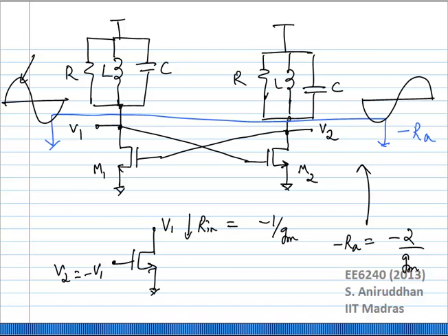Okay. Now, the asymmetry which is available between these two points, there are many different kinds of asymmetries. Obviously, if it was just mismatches between the components, that may or may not be enough to start oscillations. The reason for that is the mismatch. Let us say you have a mismatch between the transistors. All that means is that the DC operating point may be slightly different. Correct? Maybe the current does not divide exactly IT by 2, IT by 2. It's a possibility.